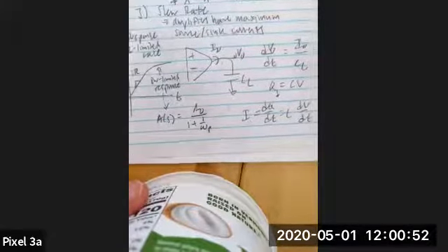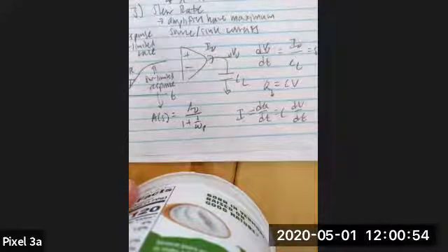I have a question on the difference between current bias and current offset. Is one to prevent the other or something like that? So a current bias, we don't typically provide external biases for our amplifiers other than VDD and VSS, which are voltage biases.